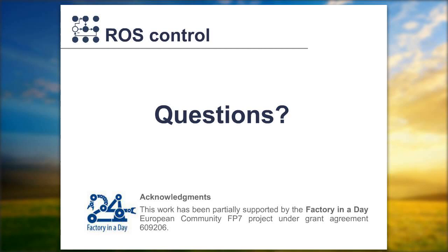Can you say a little bit more about which real-time systems you've been using this with? Yes, we have deployed ROS-Control-based systems on RT Preempt, so this would be soft real-time, and we also have deployed quite a few systems with Xenomai, which is a dual kernel approach, which allows you to have hard real-time.